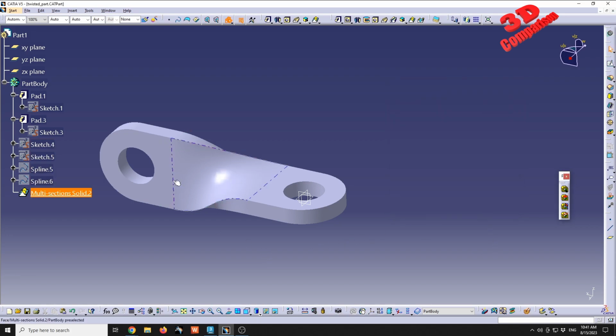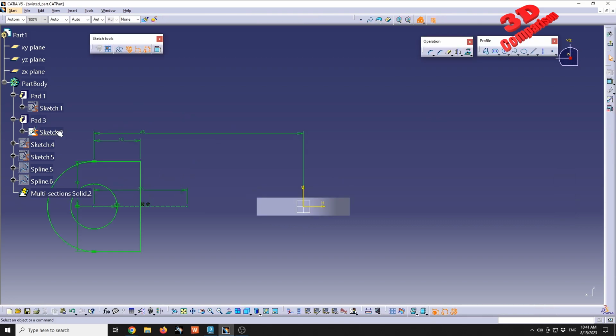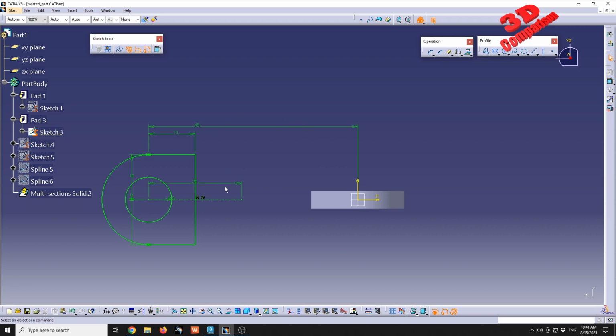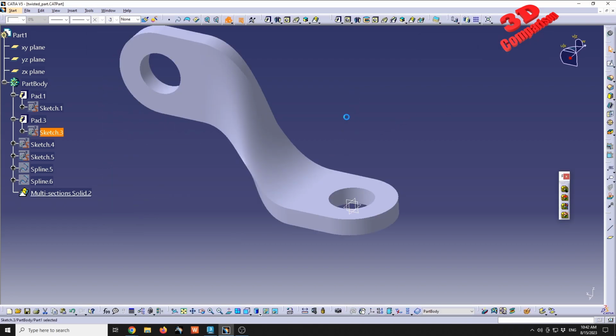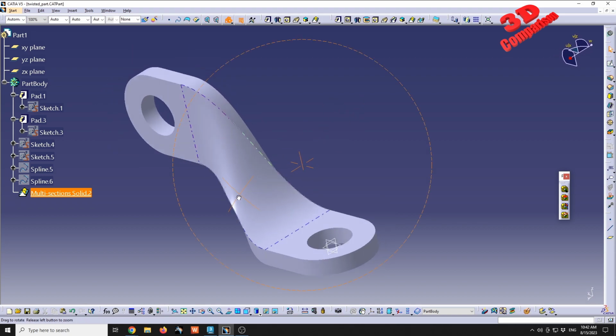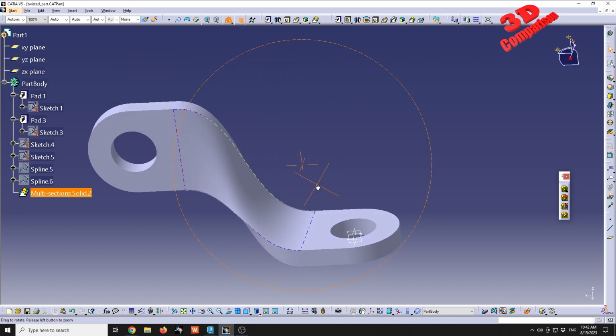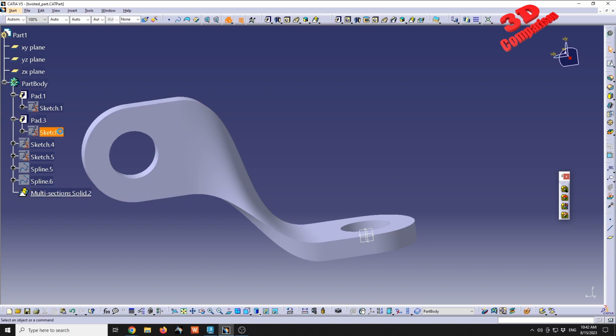Now, let's see what the main limitations of this approach are. If you want to define the orientation of those two elements that are twisted, for example, over here I added a coincidence between those two, so that axis and the original part one. I can slightly change this, like if I elevate that on the vertical axis, we're going to see that our newly created part will update and will still maintain that one-time twist.